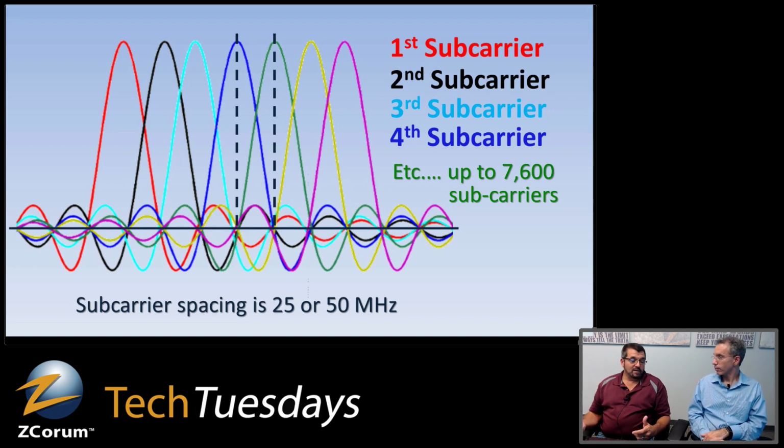So the advantage of that is for the same span, you can have a higher order modulation. You can get a 4096 QAM versus say 256, where in the SC-QAM world, it was just flat. Whatever it was, if it was 64 QAM, then everybody that uses that channel uses 64 QAM, period, across the whole 6 megahertz. In the OFDM world, because they're all sliced into little 50 kilohertz, 25 kilohertz subcarriers, each of those can be assigned different profiles, right?